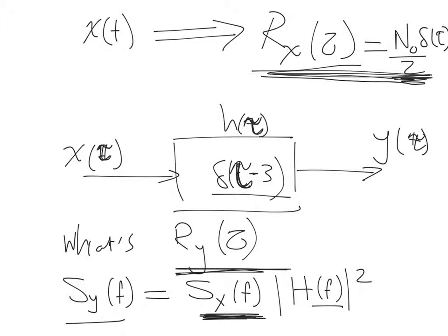A practical application of this is to study a channel of a specific band of frequency and how the noise affects it. Yes, exactly. Basically, to be able to incorporate noise into your analysis of the channel. Across the channel, you have two random processes. The transmitted signal, from your perspective as a receiver, is a random process, and the noise is also a random process. Both of them go through a channel. So if you want to calculate the output of that channel given that input, you need to apply these.